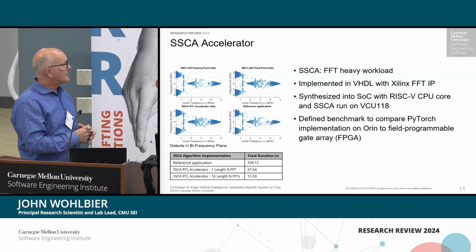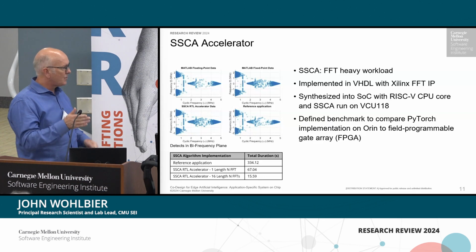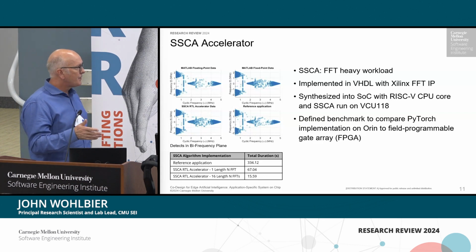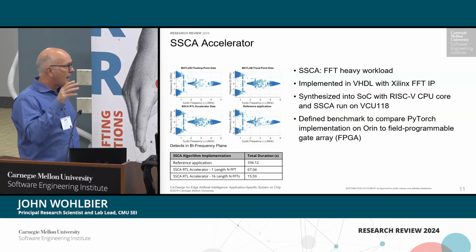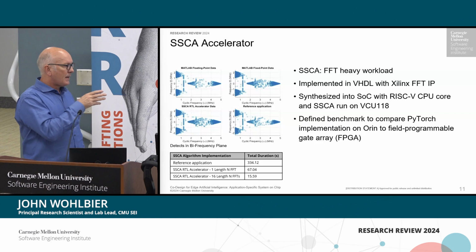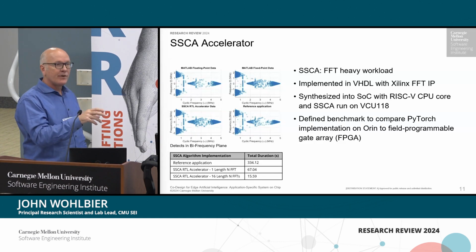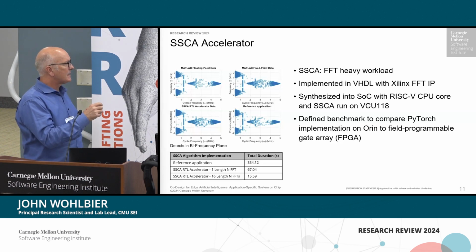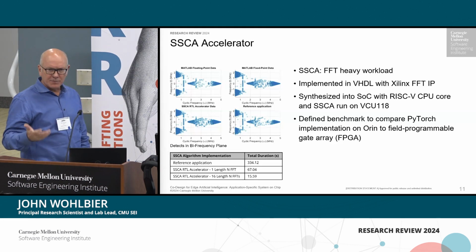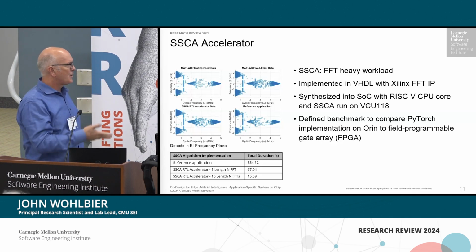All right, so hopefully I've convinced you that the SSCA is an important part of our modulation recognition application. It's FFT heavy, and we did this one by hand, in the hardware description language. There are reasons to do it by hand and by high-level synthesis. If you do it only one way, you might never know what you are missing. You can't do it for everything, but once in a while you want to take one of these things, and it's the spirit of this program or project to understand that landscape of when I should do which one.